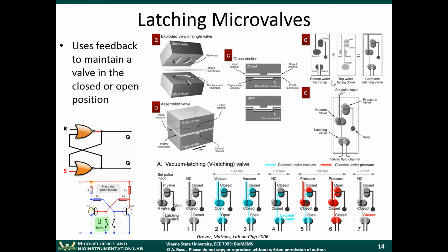Okay. It turns out there's a pneumatic equivalent of that also. It's a pneumatic circuit, a microchannel circuit that is able to remember its own state. So if you were to initially set this device to a high pressure, it will remain at high pressure, and if you set it at low pressure, it will remain at low pressure. It will remember its pressure state. I'll show you on the next slide where these types of circuits come in handy.